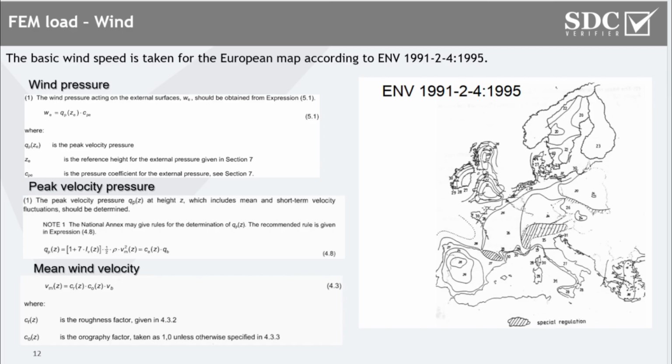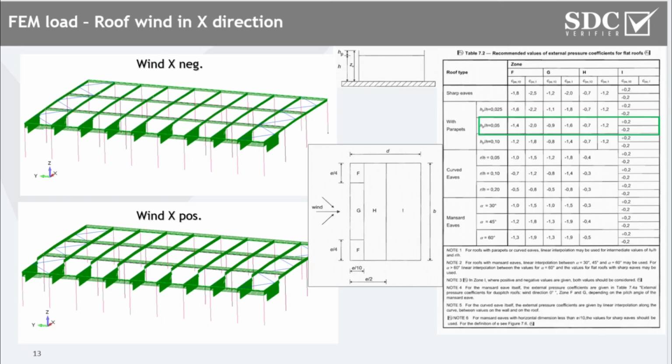This is, I would say, a pretty complex calculation, since our civil structure should be split. In this case, the roof should be split into several sectors, and for them we need to calculate the external pressure coefficients.